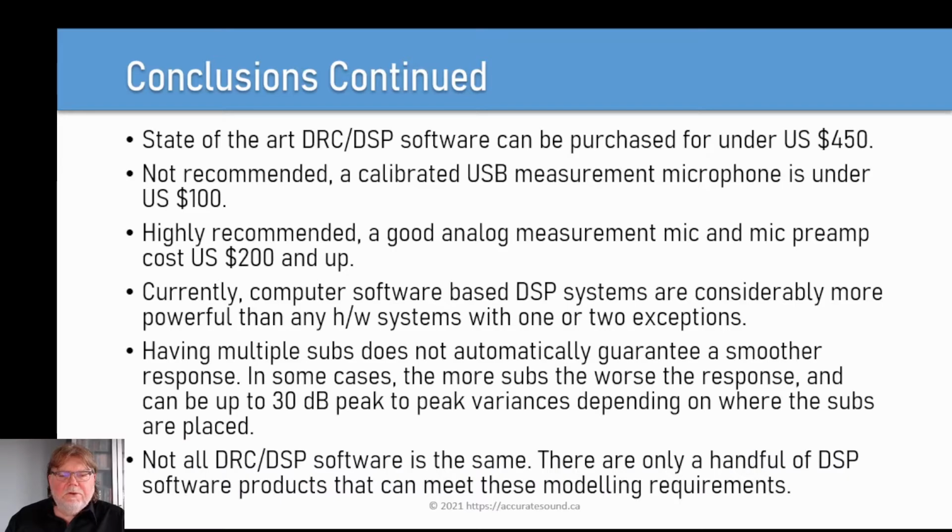While many folks are using USB measurement microphones for ease of use, there is an issue where the analog to digital converter that's running in the microphone is a different clock than what is running the DAC. So timing issues may present themselves as clock drift, or a start time for one channel may be different from the other channel. Most DSP software can accommodate this to one degree or another, but it's best to avoid the issue completely by getting a good analog mic.